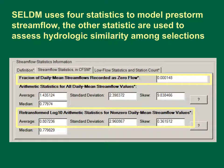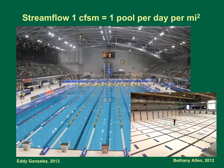SELDM uses four statistics: the fraction of zero flows and the average, standard deviation, and skew of the logarithms of non-zero flows to model pre-storm streamflow. The other statistics are provided to assess hydrologic similarity among potential stream gauge selections. The statistics within SELDM are expressed in cubic feet per second per square mile, so that statistics from stream gauge locations can be applied to points of interest with various upstream drainage areas. A cubic foot per second is enough to fill an Olympic-sized pool in a day, so we can fill one pool per day per square mile at this rate.